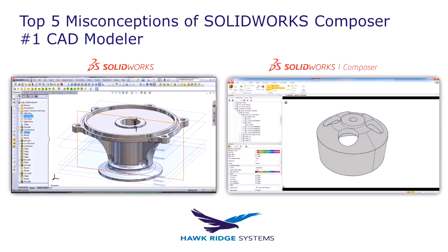So what you do with Composer at that point is you can bring this model at any stage that's in SOLIDWORKS into Composer, and they work parallel with each other side by side. So let's say that we started modeling this item here in SOLIDWORKS, and maybe we start that with a revolve or an extrude of one of these top rings here. As soon as that first extrusion is made, you can then import that file into Composer and start working in Composer, setting up your views, bringing that ring just for placement and size. And as the model is being constructed in SOLIDWORKS, you tell Composer to update whenever you want. It's just a file update, looks at the current version, updates it.